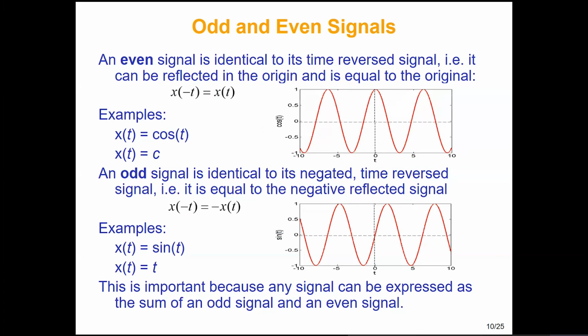We talked about odd and even signals. A signal is even if whatever is there on the left hand side, the same thing is repeated on the right hand side. So on the left hand side we have a sort of image of the same thing on this side. Then we say that we have an even signal. So whatever value is there at any instant, let's say t1, the same value will be there at minus t1. So that's an even signal, images of each other.